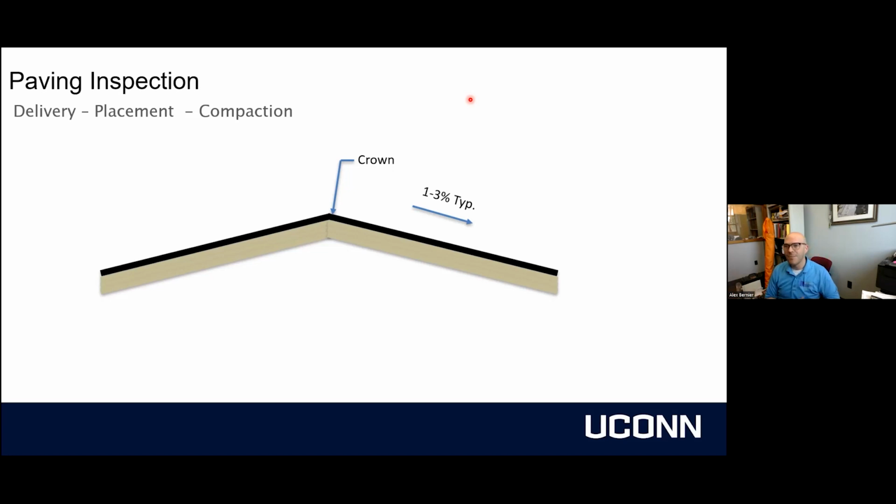And the reason being is we don't build our roads flat because that makes them prone to drainage problems. In fact, it's usually going to have as little as a quarter or 0.5% slope. In that low range, you're likely to start seeing ponding. So it's preferred to have 1 to 3% for a cross slope. We call the highest point in any road the crown, and then whatever rate at which the road falls from there, we call the cross slope.